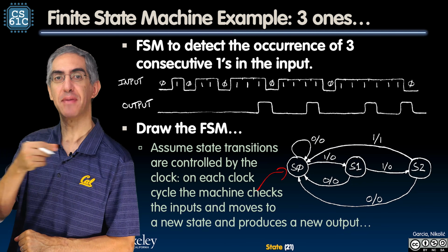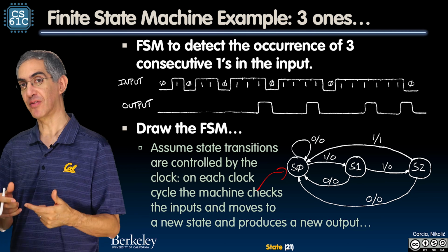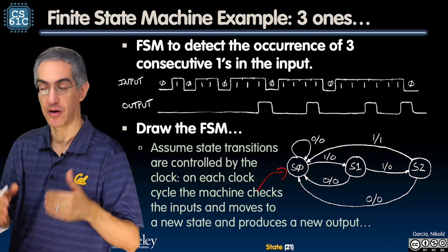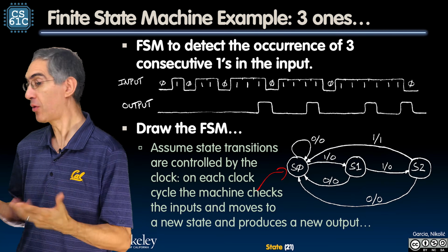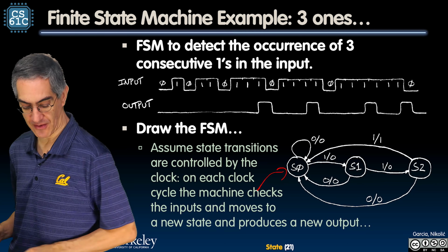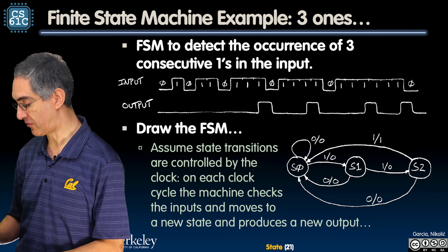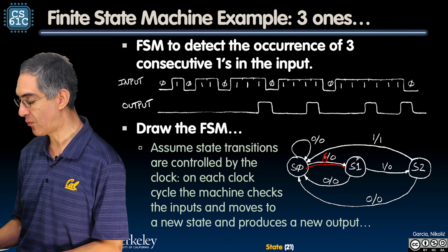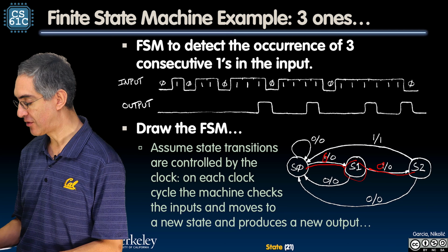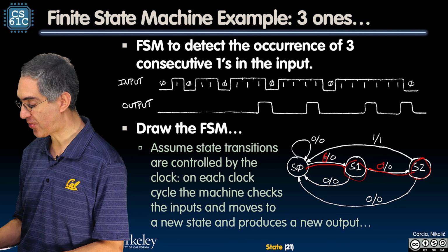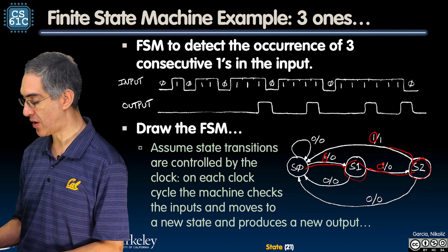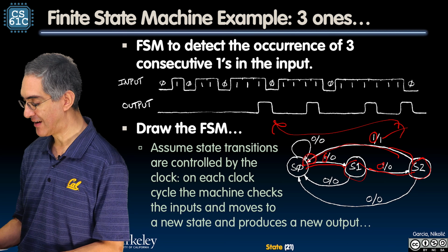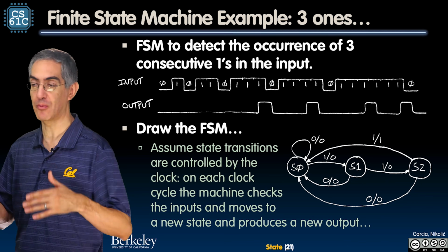And in fact, there's a semantic meaning behind this particular example, the labels of the states. We're going to actually call state 0, state 1, state 2, the number of 1s I've seen so far. So I'm initialized to have seen no 1s so far. You could also initialize to say I've seen 1, but in this particular case, I'm going to initialize to seeing 0 1s so far. And then every time I see a 1, notice this, I'm going to transition to say now I've seen 1 1 so far. Now I've seen 2 1s so far. And when I get the 3rd one, it's my 3rd one in a row, I'm going to output 1, that's why this is right here, and then reset to my initial seeing 0 1s so far. So I'm not going to say, well, I stay there.